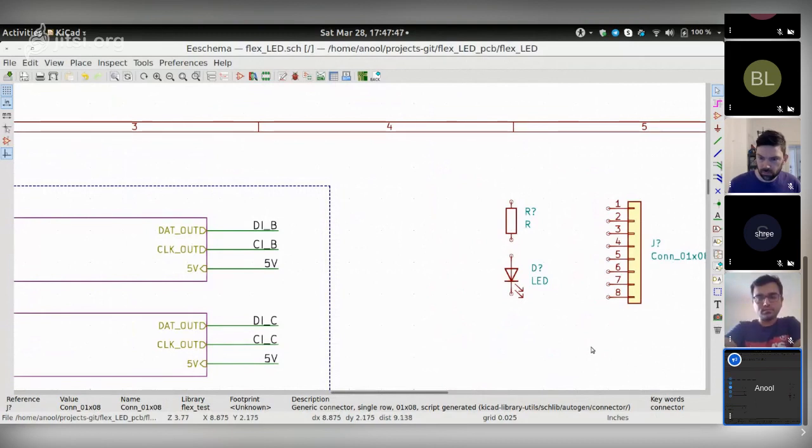So this is the way you can quickly copy parts from one library, which are global, and put it in a project-specific local library, and then use schematic symbols from that particular library instead of depending on the global libraries. It's an additional step, but as you keep working with KiCad, it's something that becomes second nature. It becomes pretty easy, and it actually makes your life much, much easier as time goes on.